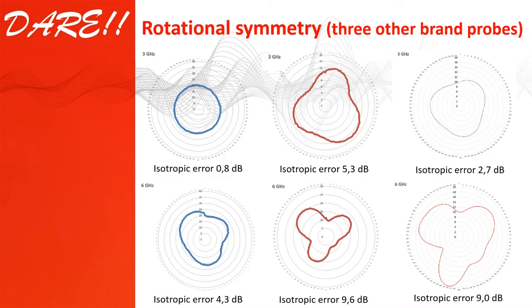And so you will see 1.6 dB, 4.3 dB, or 9 dB. That's our major differences. And take into consideration that your field probe is your absolute reference. Now, how can you handle 9 dB of error? That's quite severe.